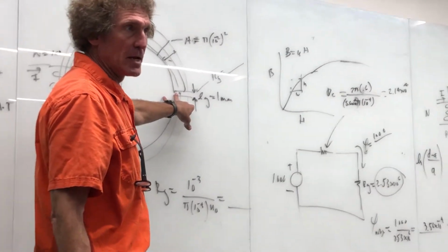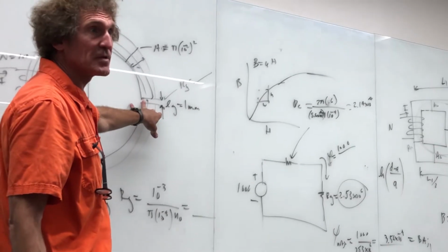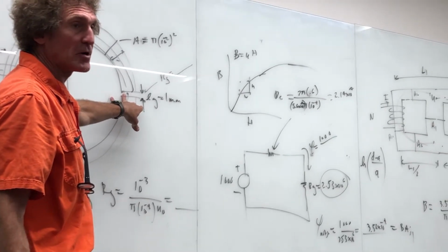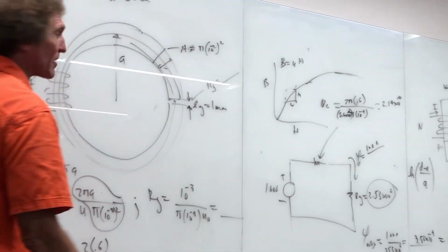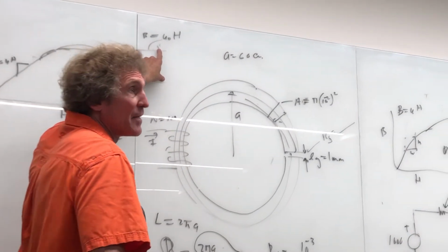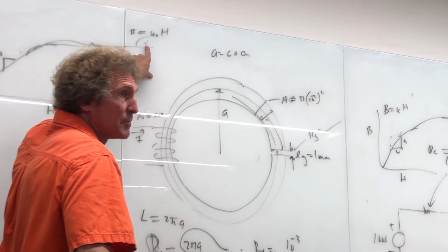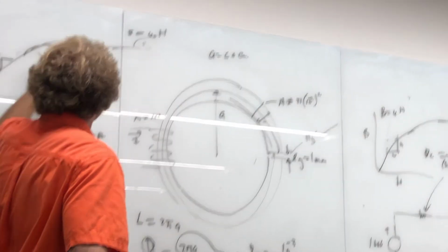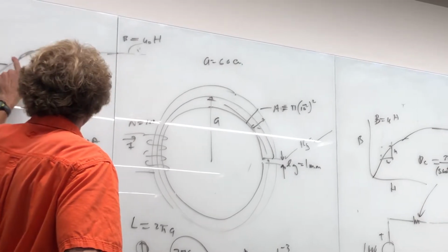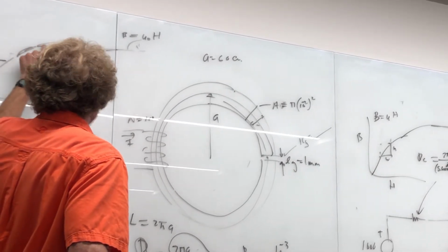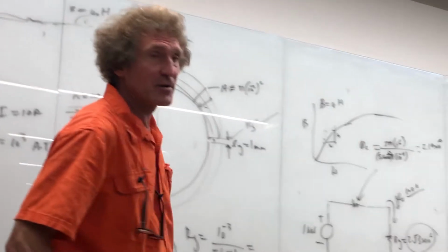If the B field is excessively large, then you start at the extremes on that graph. You start way over here. Use that value for mu, then recalculate the value of B. Now, if B is down here, then you use this value of mu and recalculate. You'll keep bouncing back and forth, and finally you're going to land on the solution.